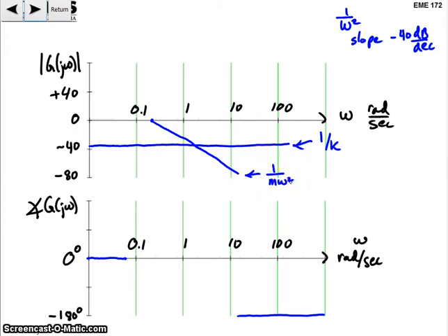Okay. Now, the interesting thing is that I have these two approximations. I have my low frequency approximation where the system looks like a spring, and that's valid well below, it turns out, something called the natural frequency for the system. And at high frequency the system looks like a mass. Call this a mass line here. This is the spring line here. It turns out that these two things will intersect exactly at the resonant frequency of this system.